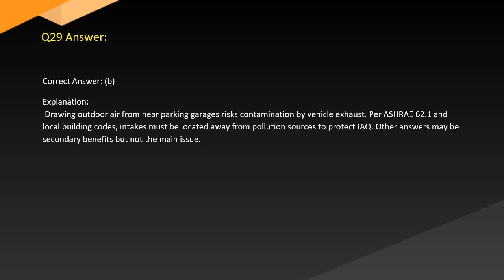Answer. Correct answer: B. Explanation. Drawing outdoor air from near parking garages risks contamination by vehicle exhaust. Per ASHRAE 62.1 and local building codes, intakes must be located away from pollution sources to protect IAQ. Other answers may be secondary benefits but not the main issue.